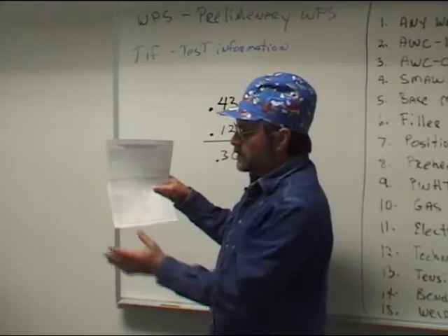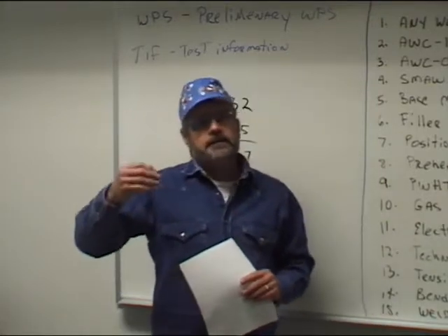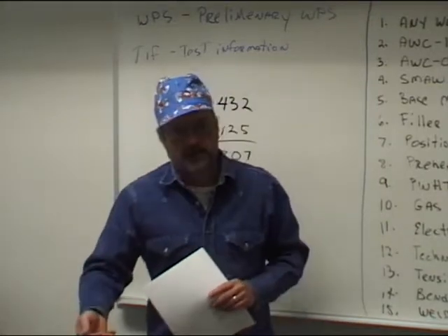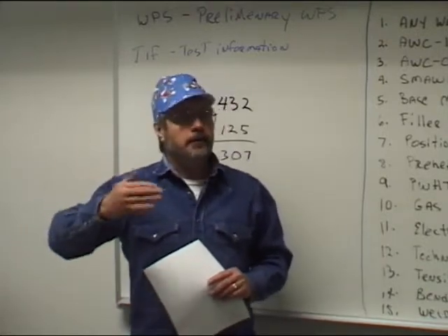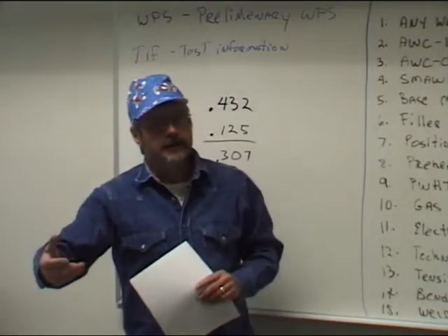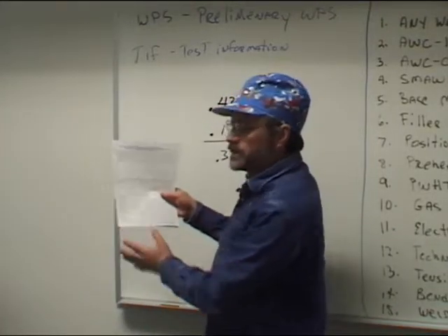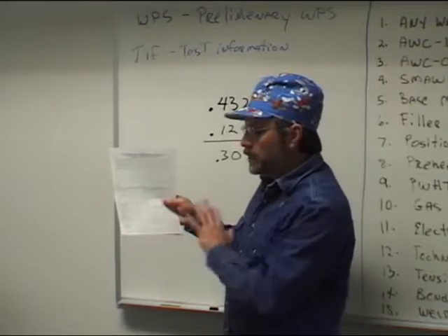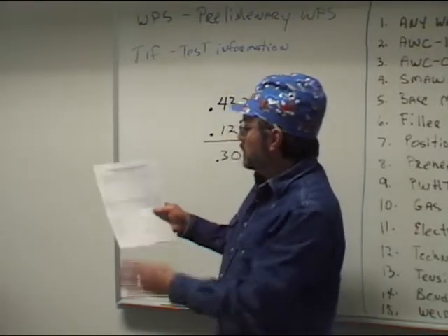And then your interpass temperature. Now your interpass temperature, as the name implies, are those passes that happen after the root pass is put in, but before it's capped. So those are the ones that are in between during the process of filling it up. Now you would check that from time to time and record the interpass temperatures in here, and that would help you to establish a maximum interpass temperature later on.